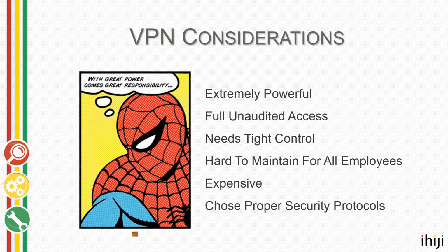Use it on all your installations, but don't give the credentials out to anybody except for your IT admin. And everything that requires VPN access should be escalated to that one person. And get out of the habit of using the same username and password for all of your sites. Get out of the habit of using things like LastPass to track all these usernames and passwords. And limit who has access.